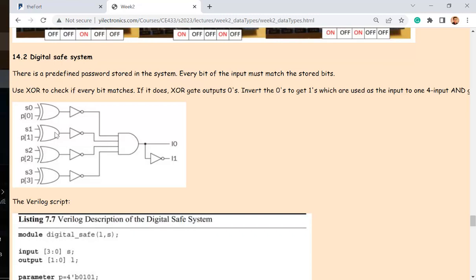And now let's look at the logic, see if that makes sense. These are XOR gates. So what's the logic for XOR gates, remember? The 2 inputs have to be what? Then you are getting a 1. For XOR, exclusive OR, right? They have to be different. They have to be different in order to get a 1. If they're the same, doesn't matter if they're both 0s or both 1s, you're getting a 0 output. So that's why we only use an XOR gate here to match the 2 inputs.